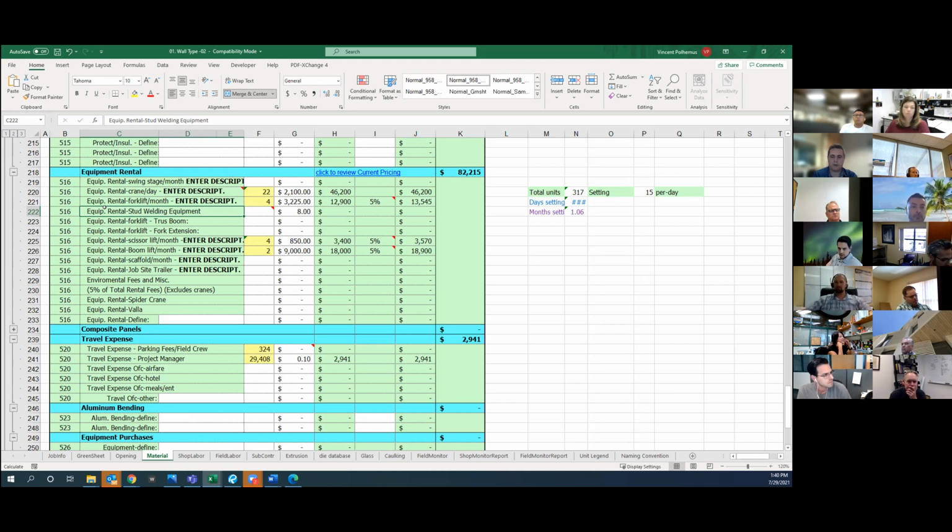And those of you that have run a South Bay job have probably heard from the field that they're not the most perfect jobs. We bounce around. We do favors for them. Like, we do all kinds of stuff, and we don't go back for change orders, right? We have to make sure that we have those inefficiencies covered. So while TJ may think and plan that we're going to set 20 units a day with a crane, we figure all of our crane setting as 15 units, not 20.